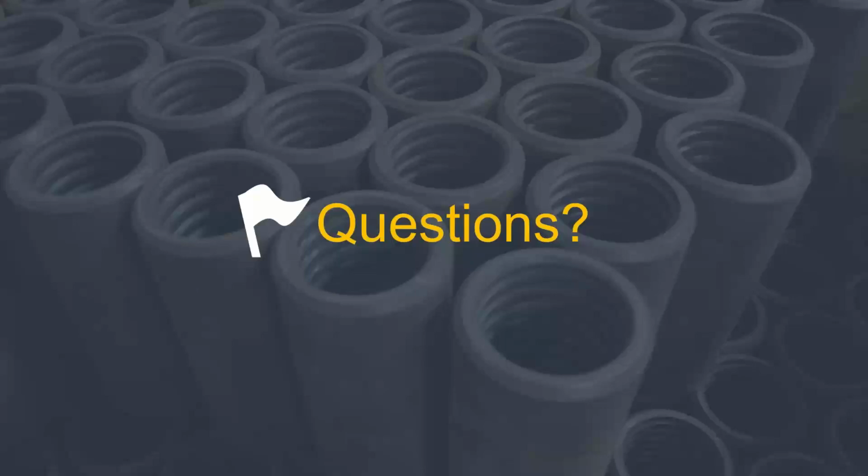Okay, now I have another question regarding pile groups. Typically in warehouses, they might be 30, 40, 50 kip piles. The question is the total pile load. My question is, putting in 3 piles is not cost effective, and the size of the pad, the cap, will be big. So we do see sometimes 1 or 2. Now, I know 3 is preferable, but how can you compensate for that besides grade beams? I don't know if there is a way.